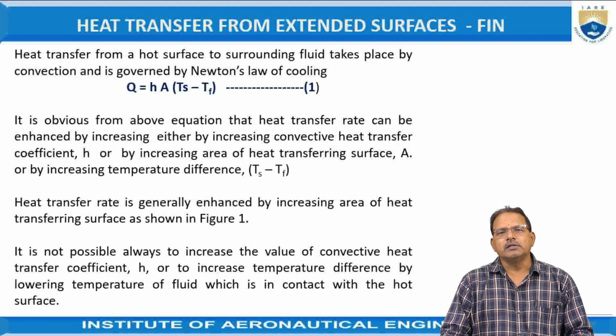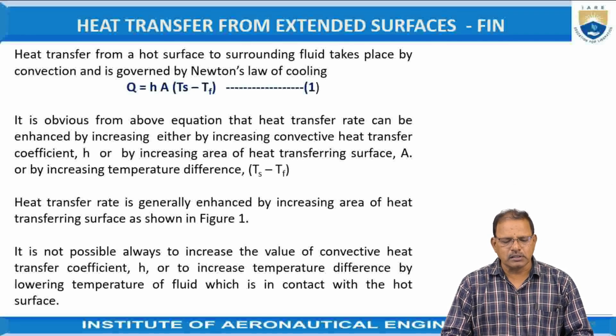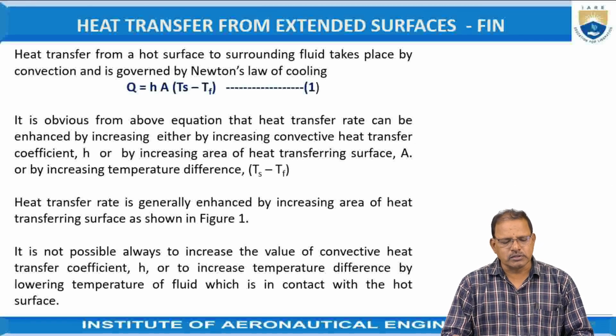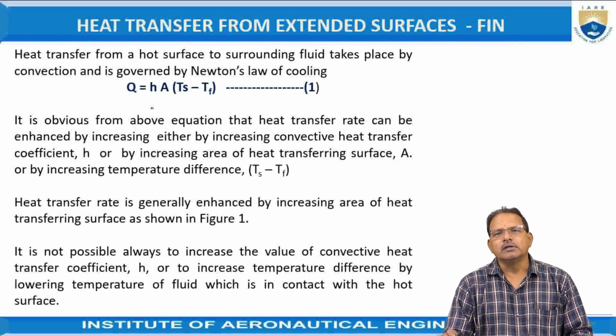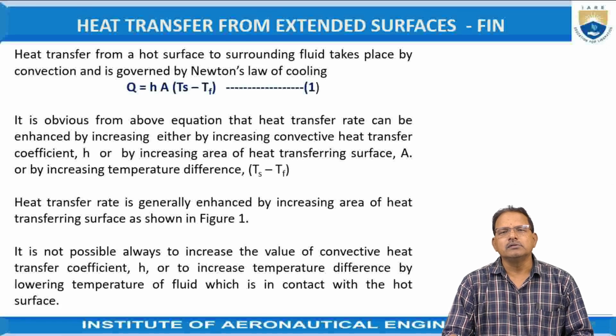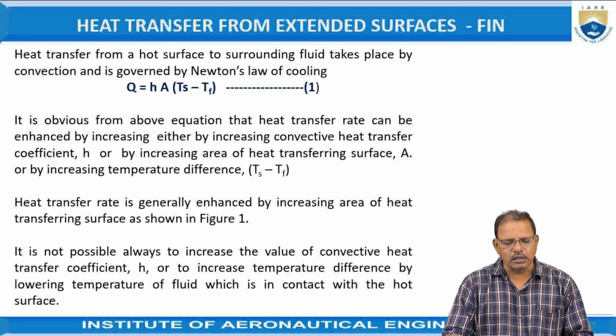The amount of heat energy flowing from the fluid to the surface is given by Newton's law of cooling: Q is equal to h into A into (Ts minus Tf), where Q represents the magnitude of heat energy transferred from the fluid to the surface, which is maintained at a temperature of Ts. h is the coefficient of heat convection process. A is the surface area.